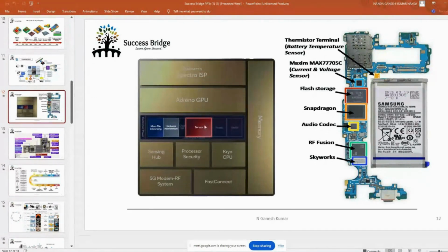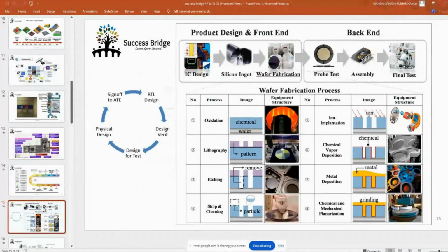Once the RTL design engineer writes the code, he will give that code to the verification engineer to verify it. Okay, so the verification engineer has to write the test case to verify that RTL module. Let's say module AND gate, with inputs and outputs, and there is a logic of AND behavior. Okay, C is equal to A and B. So this behavior of the module, he has to verify. The verification engineer has to verify by providing a test case or creating a test case.